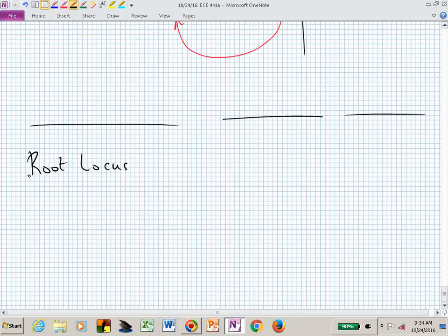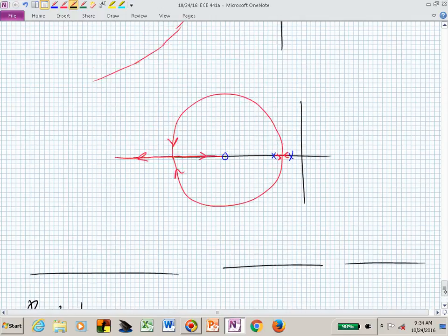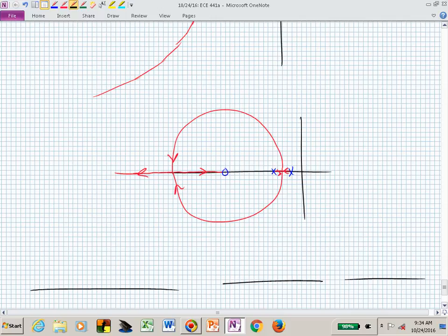Now do you see for that particular system, the only possible closed loop poles for that structure live on that red curve. We can't go anywhere else with our closed loop poles. Meaning, if you now wanted to achieve a certain settling time, and I don't know why I drove it right through 0, it didn't have to be. Suppose that I said I want a settling time that gives me that yellow line.